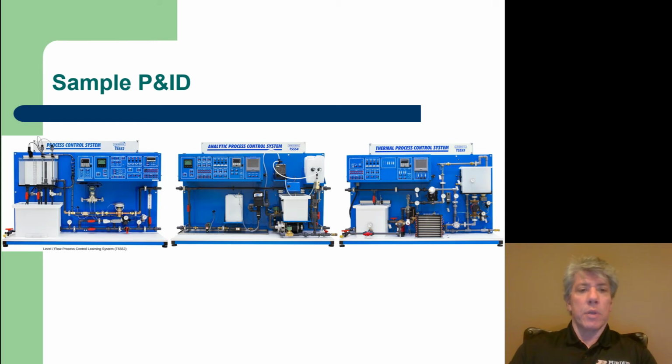There's a little instrument tucked up under the cabinet, sort of in the middle. It's blue and has some lines, clear lines coming down from it. That is a flow measurement system that measures flow by a pressure drop across some type of a flow restriction.